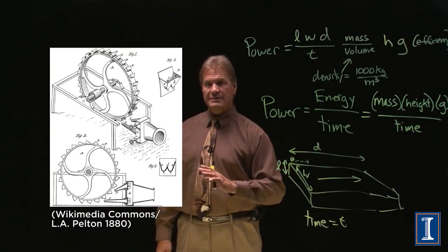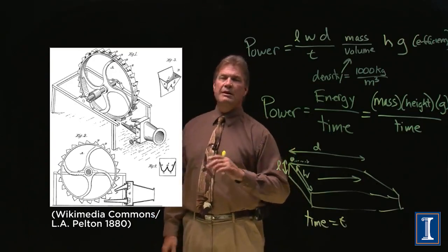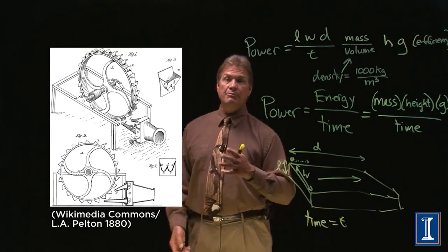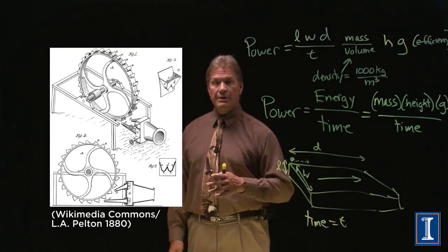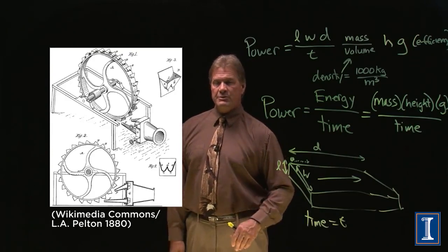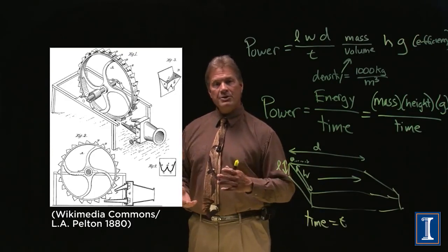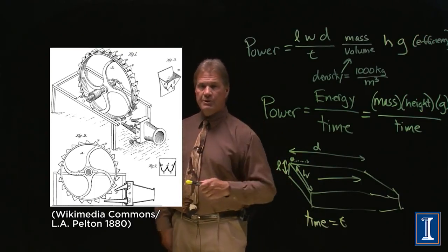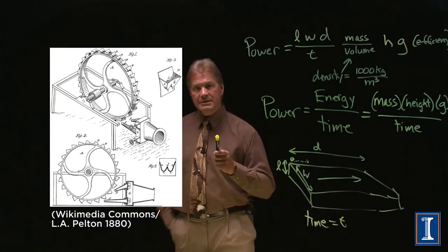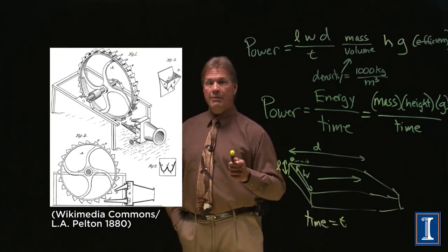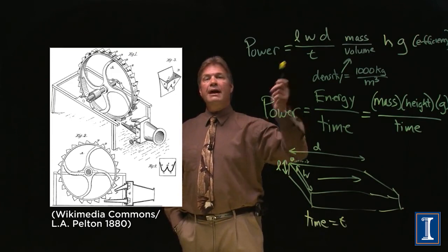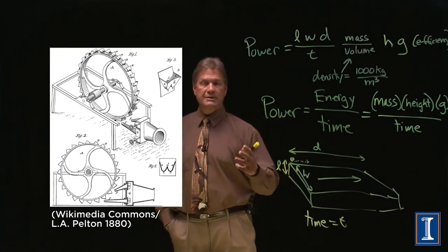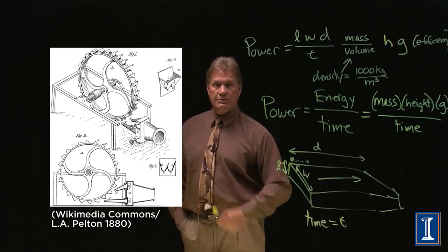Those types of turbines, these small scale turbines, have 0.4 to maybe 0.8 efficiency, I'd say something like 0.6. And the 200 watts we calculated was assuming a 60% efficient turbine. If you don't have a lot of pressure, you don't get as high efficiency. Of course, this type of turbine is also useful in that you don't necessarily need to make a dam. You could just have the water coming down the hillside, and the pressure from the water itself could turn these, just like you see in many places where they use a water wheel to do some type of work.